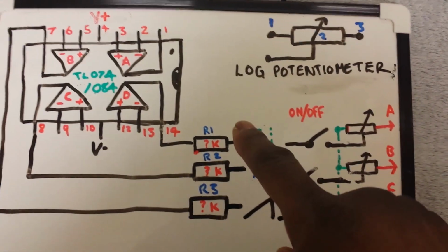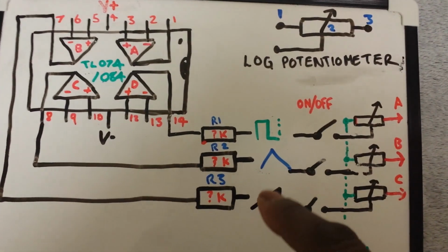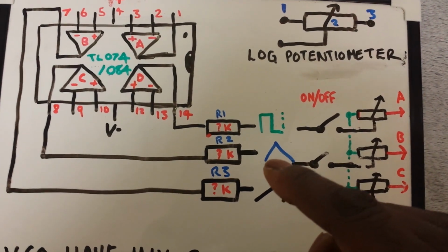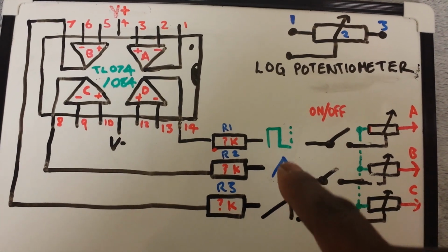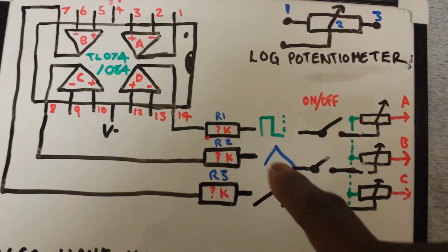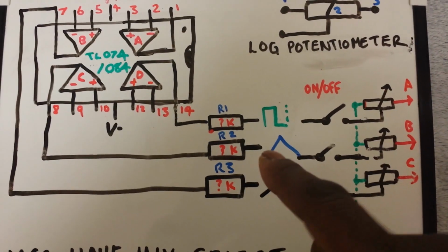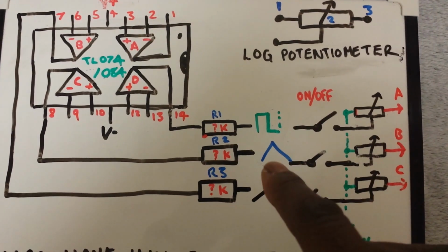So now we have all our op amps out. We need to find out which one of these outputs is going to be the lowest, and what we need to do is make sure every other wave shape matches up in amplitude. So say for instance 9 times out of 10, could be less, 8 times, our triangle wave will be the quietest wave shape out.